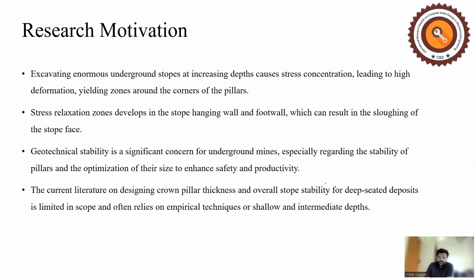The motivation for this research comes from a cross section of the same stope which I explained earlier. Let us consider this stope is empty and completely extracted. After extraction, the stresses will be redistributed in the form of an arch. During this redistribution of the stresses, the existing joints will be enlarged and widened. In this process, the stresses will get released, so this zone becomes a stress relaxation zone.